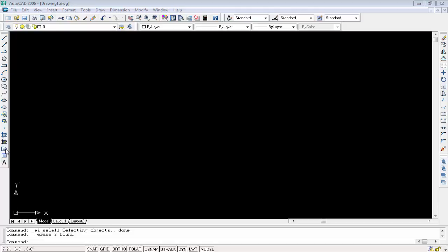But before extruding, you should region all your drawing. I mean, you should put your drawing in a group form. So the region tool is specially created and used for this purpose.